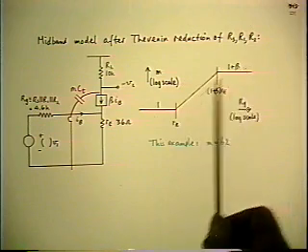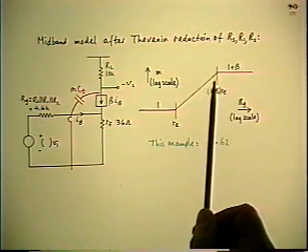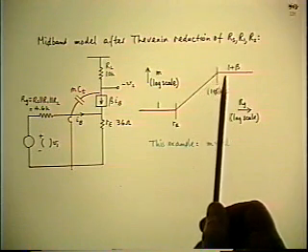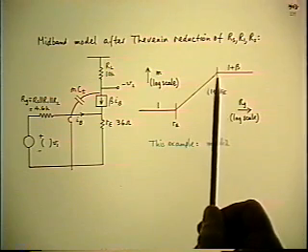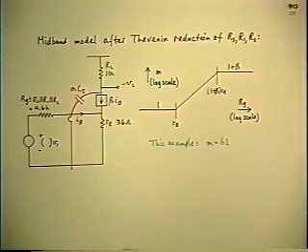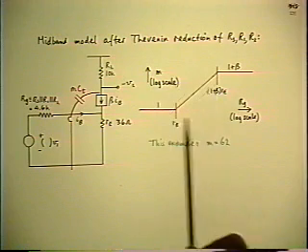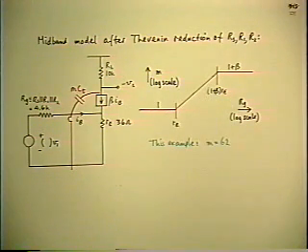Likewise, at the other extreme, if you're not that concerned about bandwidth and you like to use a high Rg, by the time you get to an Rg of (1 plus beta) Re, the bandwidth is as lousy as it's going to get, and you can make the Rg much larger than that and you won't be any worse off. So you see there's a lot of useful interpretation you can get out of that little sketch.